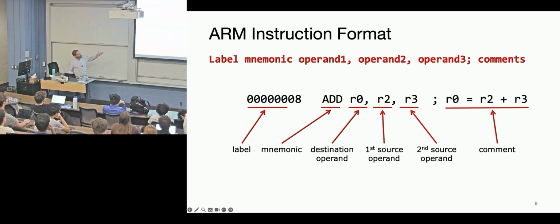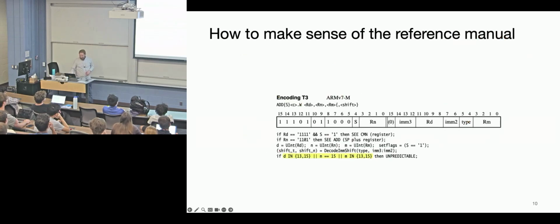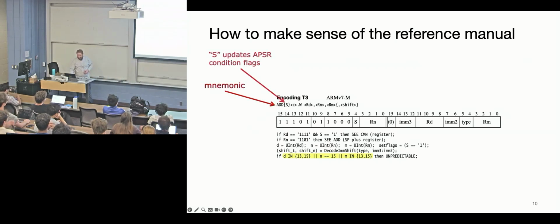So, these are the general structures that you saw in 370. If you're trying to read the ARM7 manual, this thing is kind of horrible to try and decipher. When you're an expert on embedded systems, then you're like, aha, it's super useful. It's very bad for learning. So just as a reminder, there's a mnemonic here. The S flag is an optional flag that tells the assembler that this instruction should set the conditional flags, okay? So you don't have to set the conditional flags. This is just the mechanism that you could use to do that.